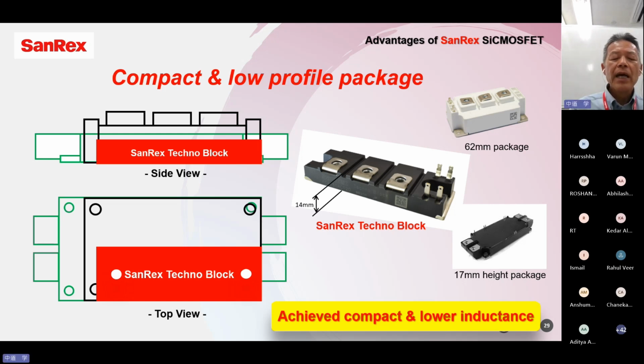From side view, this is the market standard 62 mm package. This is the market standard 17 mm height package. And SanRex Technoblock is this height, very low. From top view, this is the 17 mm package. This is the 62 mm package. And the SanRex Technoblock package is only this size. You can see how small and compact SanRex Technoblock is. We achieve compact, lower inductance as well.